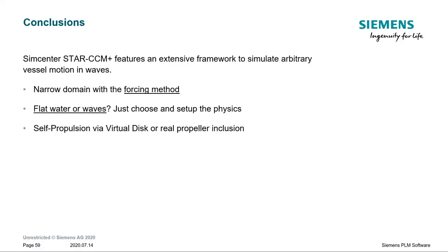If you want to include self-propulsion, you can do it via virtual disks, via external forces, or even with real propeller inclusion and superposed motions. Maneuvering, again, is not a problem because you have your DFBI motion for the vessel, and whatever position the vessel will take, the moving forced wave tank will follow it.